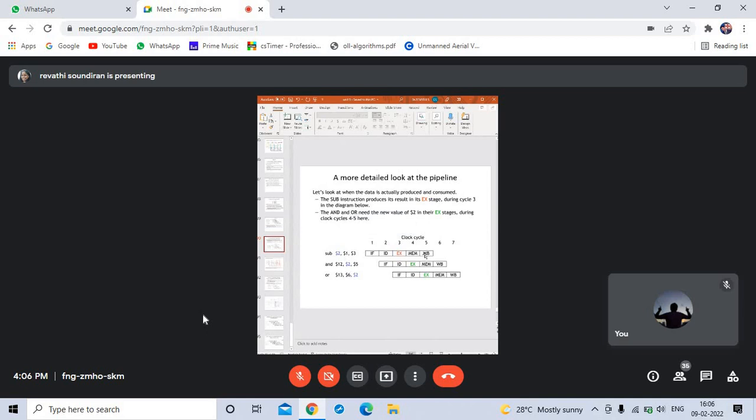And you have to understand that what is read here is not an updated value. It is an older value, which is available in the second register. That is the problem created due to this pipelining concept.